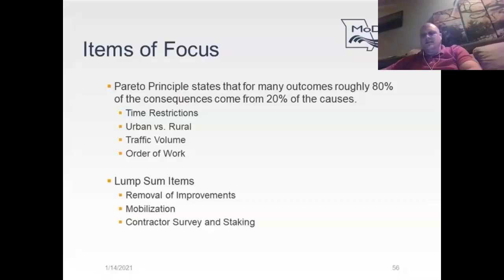Most of the time, you can come up with a cost for those. If you're replacing, say, a pipe, and you know the installation cost of that, you know that the price for removal isn't going to be as high as that price that you looked up in history, because that price in history is all inclusive: material costs, labor and equipment, etc. So for a removal price, it would be something less than that.